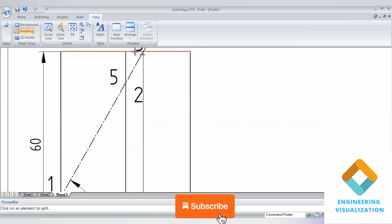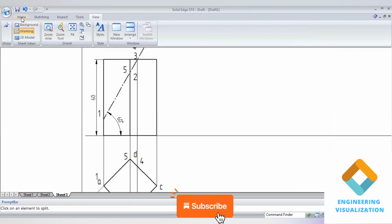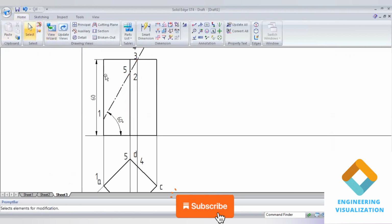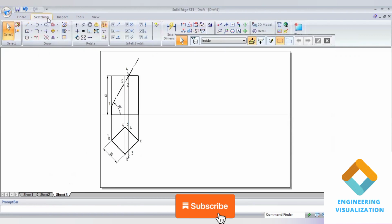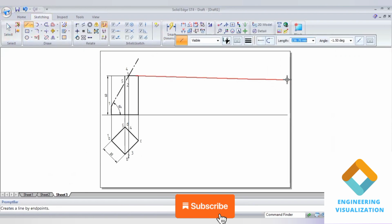I can use the split command to highlight only the retained cut portion. Using the split command we can split it exactly where we want to make the lines dark. We have to darken only the portions which have been cut by the section plane, the retained cut portions. The other lines I am going to make thin lines by selecting them. Now we got the cut portion, and now we have to do the development.